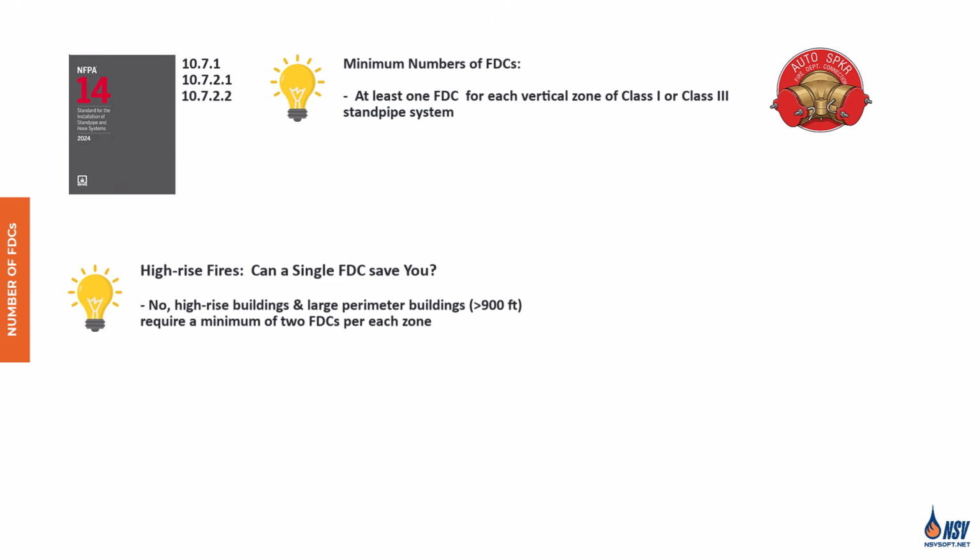In large buildings, it's common to see multiple fire department connections installed at different locations. When a facility is served by private fire service mains that feed standpipe systems across a wide area, additional FDCs help ensure the fire department can effectively pump water into the system from multiple access points.